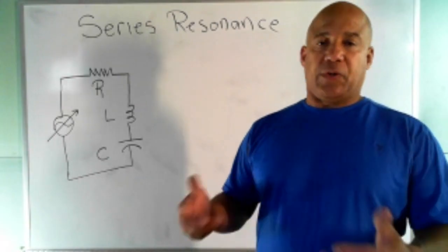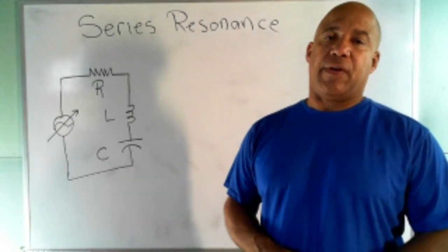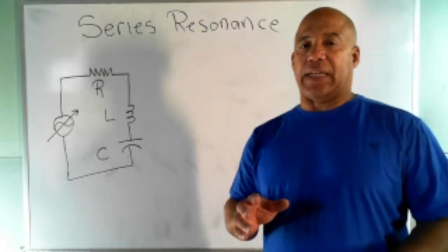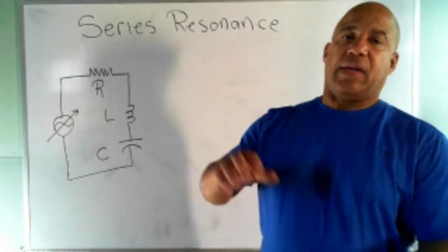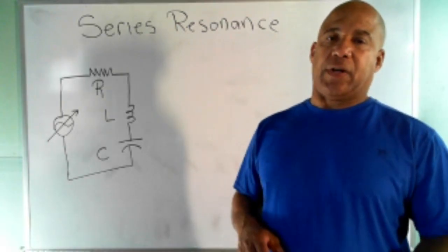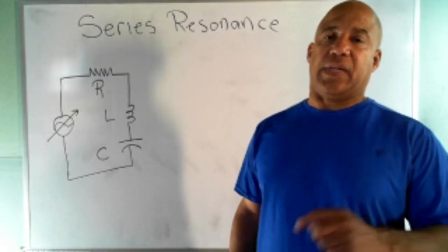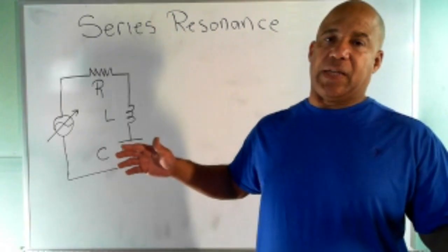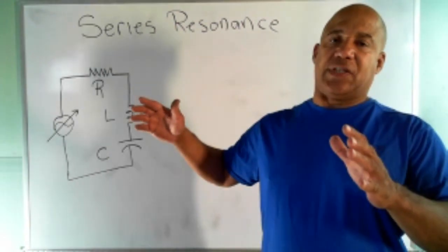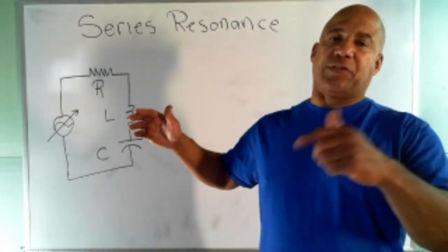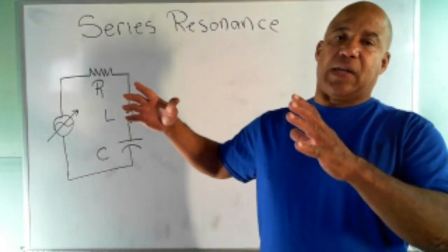But so do circuits. I showed you how you can put energy into a capacitor, and if I have an ideal capacitor, it'll hold that energy forever. But what I did was hook it to a switch and an inductor, and we made a circuit where when the switch is closed, the capacitor will discharge through the inductor and build the magnetic field up around the inductor. As long as the current is flowing from the capacitor to the inductor, that magnetic field is sustained. But when the capacitor discharges, there's no more current to maintain the magnetic field around the inductor, and it starts to collapse.